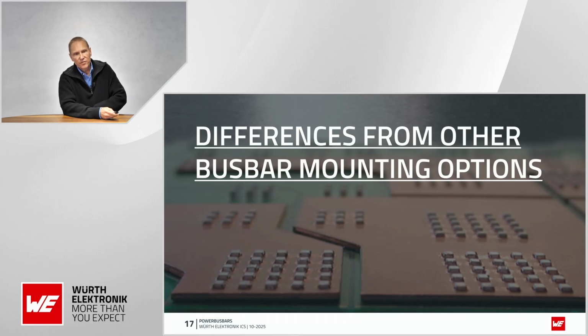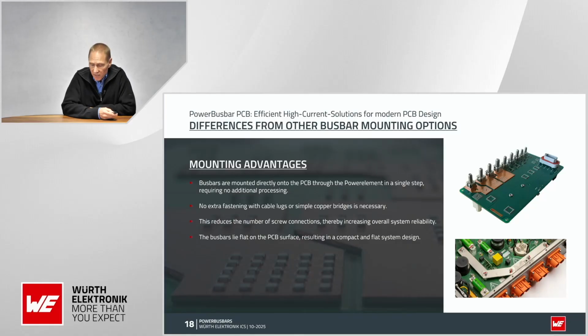But what is different from other mounting options? We see mounting advantages when you use such a system. At first, the bus bars are mounted directly onto the PCB through the power element in a single step. So there is no need for extra fastening or an extra processing step.